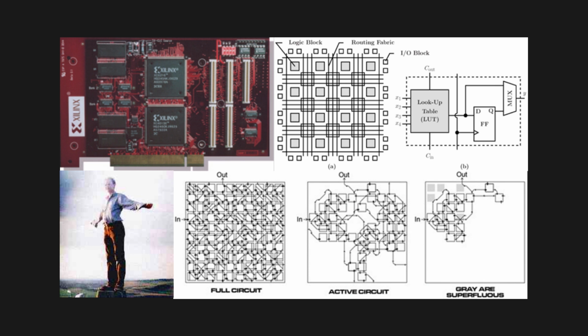Firstly, the circuit was evolved in the absence of a clock, suggesting that evolution independently generated complex internal circuit dynamics for determining frequency. Secondly, the number of configurable logic blocks, or CLBs, used on his Xilinx XC6216 field programmable gate array was a parsimonious 42 out of the available 100. And lastly, perhaps most magical of all, the circuit that evolution created employed untraceable physical phenomena that was not directly accessible on the genotype-phenotype map. To this day, the hidden characteristics utilized by the circuit are not fully understood.